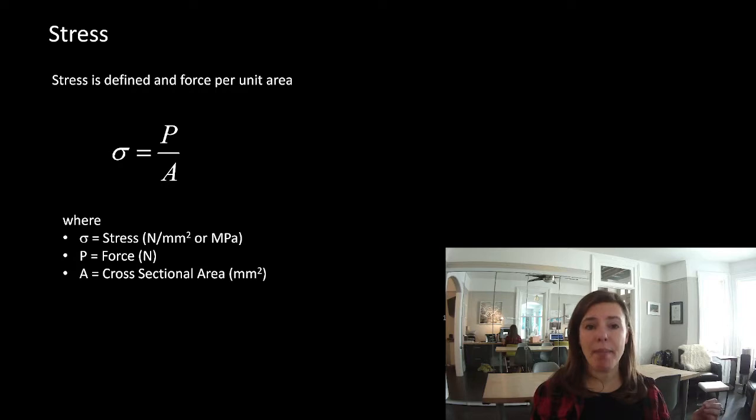So this is a good way to remember it. When we're talking about force and deformation, we're usually talking about kilonewtons and meters, unless we're talking about the exact amount of deformation, and then often we'll put it in millimeters. Stress and strain, we almost work exclusively in newtons and millimeters. But they relate back and forth so easy. That's the beauty of a base 10 system.